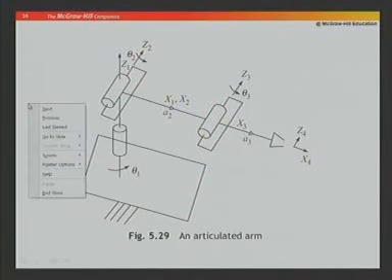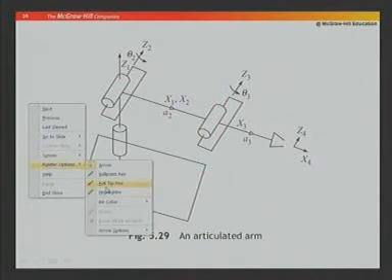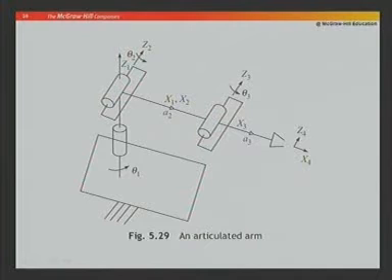Okay, let me take this pointer. So, this is Z1, this is Z2 and this is Z3. Please note that I could have done Z3 in these directions also, there is no harm. I just took Z3 parallel to Z2. Now, if you remember the definition of DH coordinate frames, the common perpendicular to Z1 and Z2 is x2.